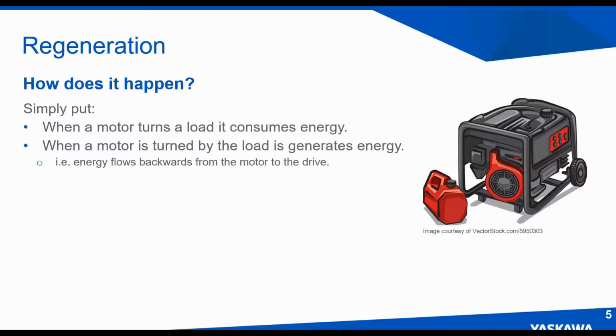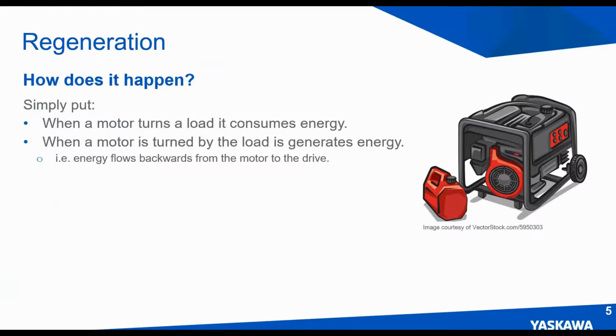So regen, how does it happen? When a motor turns a load, it consumes energy. Like when you're pushing on a door to open it, it's going to take some energy to move that door. However, when a motor is turned by the load, it regenerates. The motor turns into a generator.